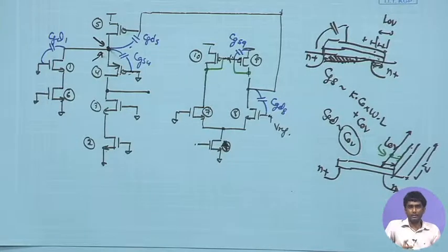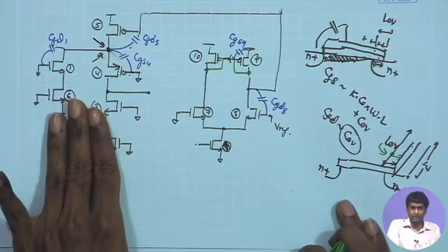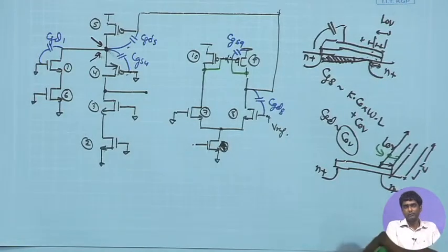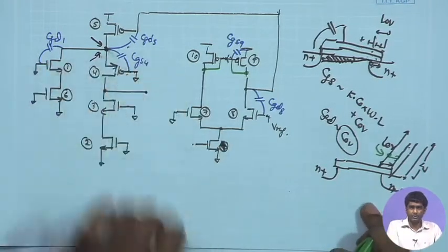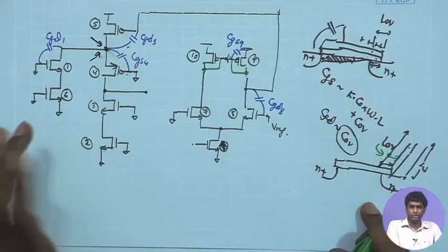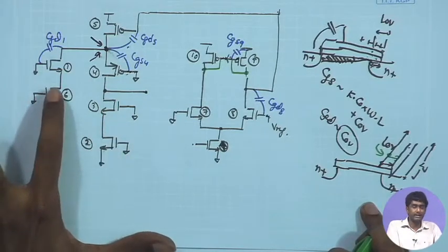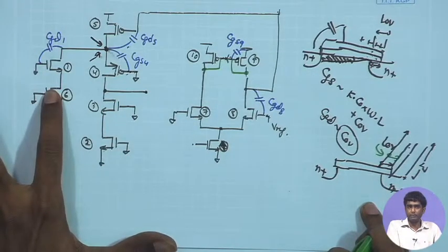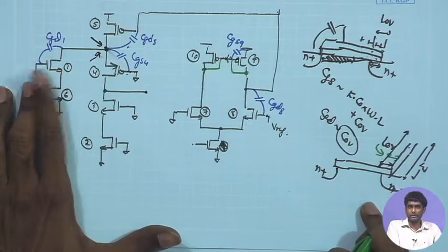If I look at the considerations that we are already aware of, for example, if we want to have a good gain from the cascode amplifier, I would like to have the gm ro product to be large. For that, I would like the W by L of the input pair over here to be large. So, that is again conflicting.